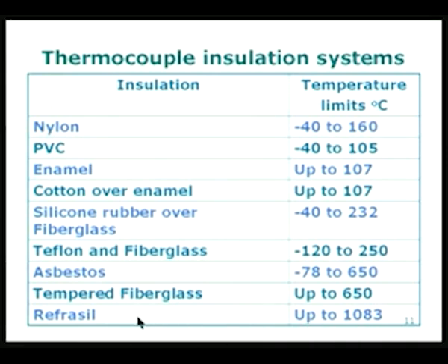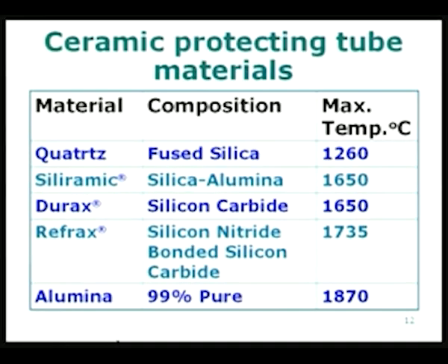So these are the normal insulating materials which are used, and in case we do not have any material which can be used for the insulation, we may have to use the two wires run separately away from each other, for example, like in electrical heaters, where the heating elements have porcelain beads. We can similarly use porcelain tubes or porcelain beads to do that.